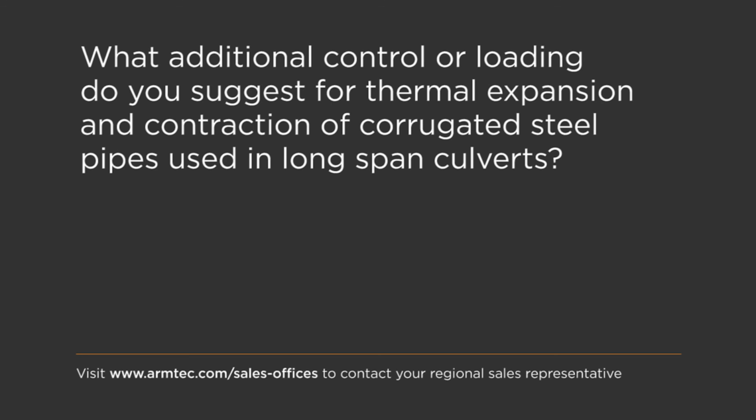Mm-hmm. And I think you've kind of answered the next one related to the far north, which is what considerations are used for embankment fill experiencing a lot of freeze-thaw cycles, which I guess you said needs to be free draining is the biggest consideration. Is that correct? Yeah, correct. As well, the movement in the steel portion itself is not a large worry for us because they are meant to move and flex.